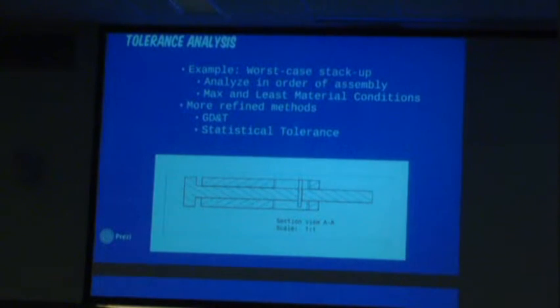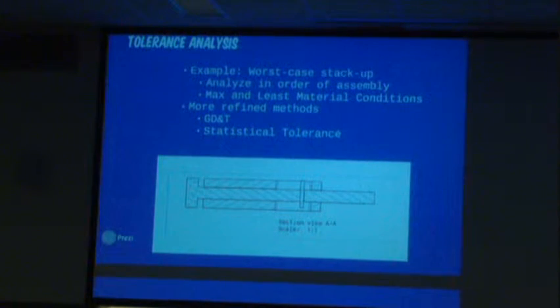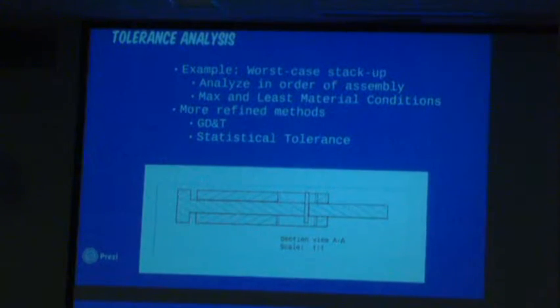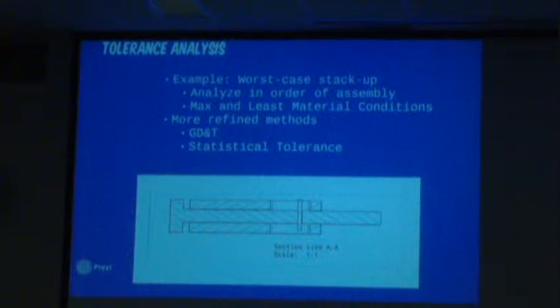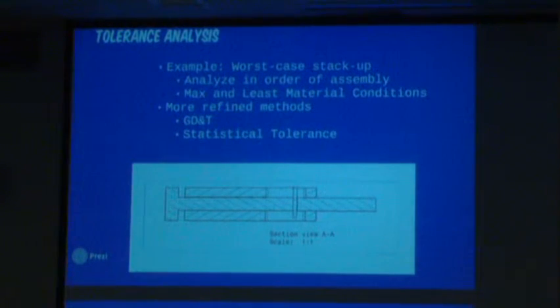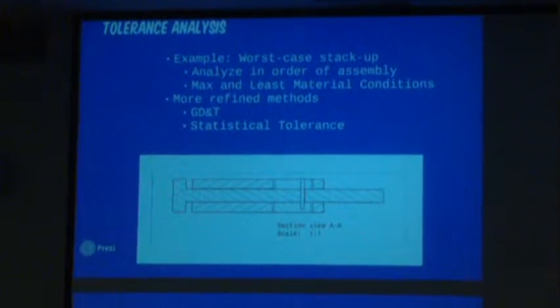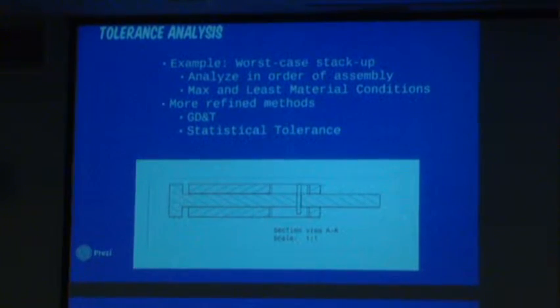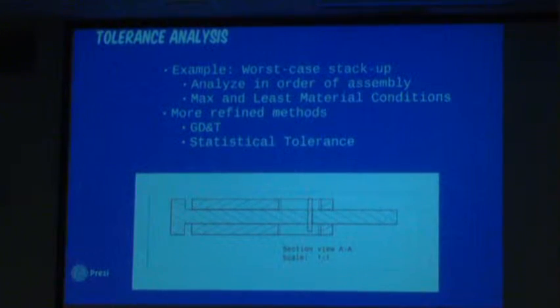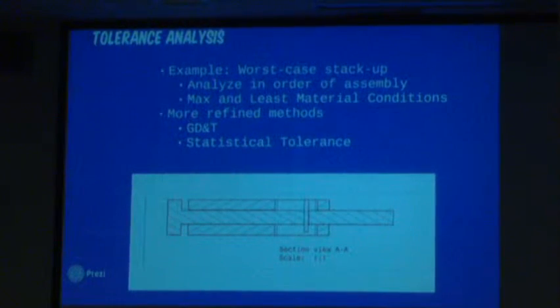So with that, you could dimension those, and then for each dimension in the print, you'd go through and do a similar exercise. If you do this a couple of times, you'll start to see where the math comes from, and you can skip most of that algebra. In fact, I'm not sure I've ever done that on a real print. You just look at it and say, I can calculate that I've got 1/2 millimeter between them, so I know I can go 1/2 millimeter of tolerance overall, and then just split it out as you need to. So common sense will come to rule once you've done this a couple of times and you understand where the numbers come from. So any of you who are going into mechanical or civil, you'll definitely do this.